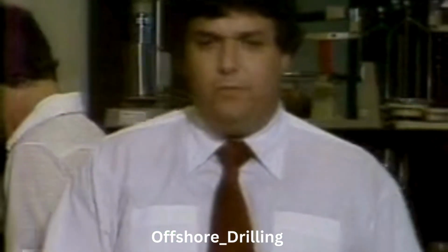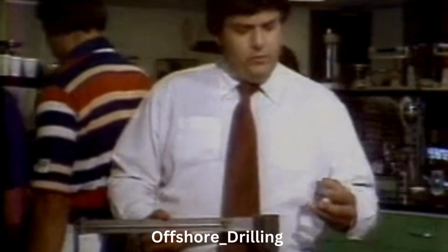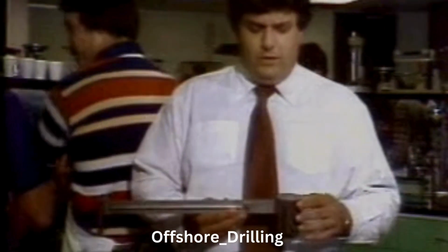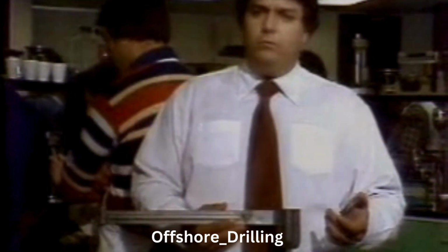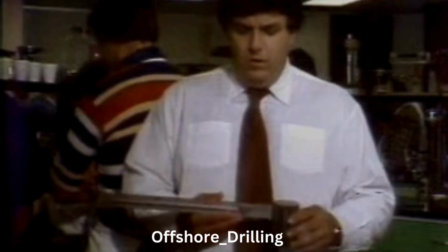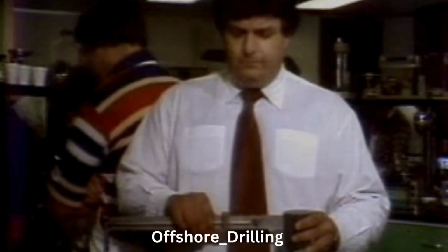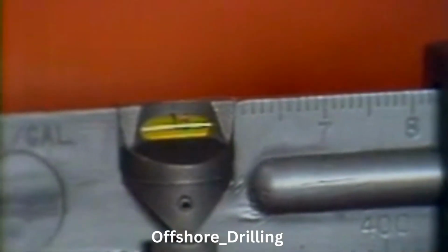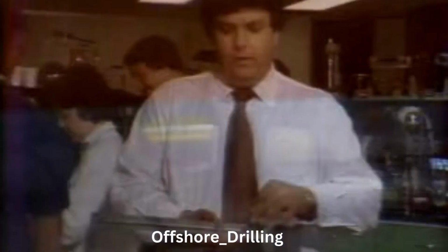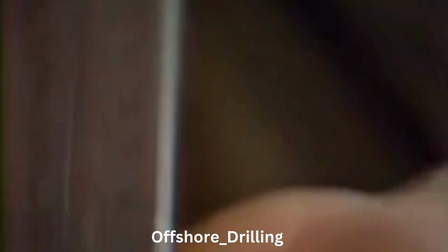In using the standard mud balance, 3 points should be made. First, the lid. The lid received with the mud balance should be one that's always used with the mud balance. It's a calibrated instrument, and the changing of this lid could alter the reading of the drilling mud. Secondly, the calibration. Water weighs 8.3 pounds per gallon. Calibrate the instrument by placing water into the bowl. Water, when balanced, should split the hair that is shown on the balance bubble. If it is out of calibration, it can be calibrated by either adding or removing lead shot found on the end of the scale.